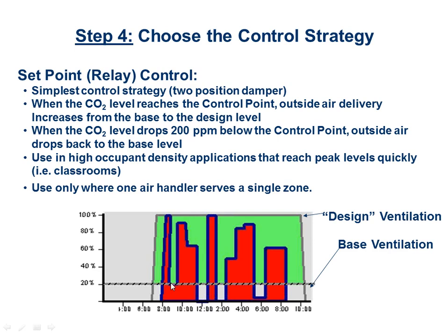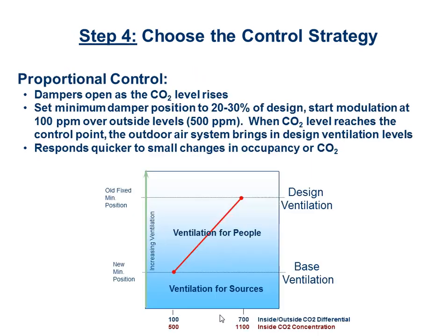And then a few minutes later, I would see that my CO2 level started increasing again. So I'd open the damper, and close it, open it, close it, open it, close it, which is basically ping pong between the design ventilation that the code required and the minimum base ventilation that the square footage portion of the code requires. It would ping pong between those two numbers. It's a pretty crappy way to do it, but a lot of the old economizer controls could handle it, so that's the way we were doing it.